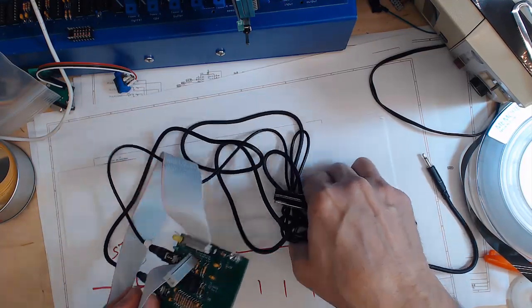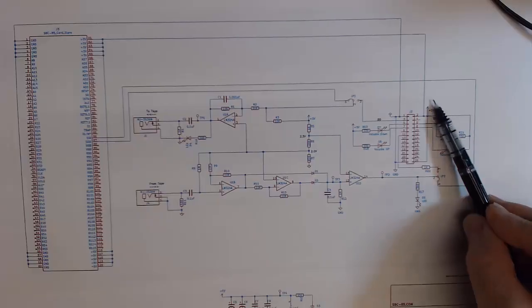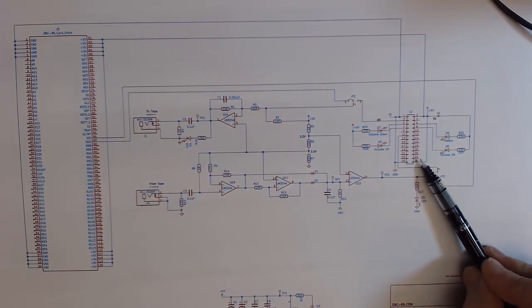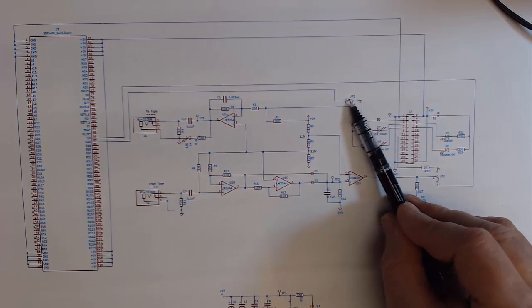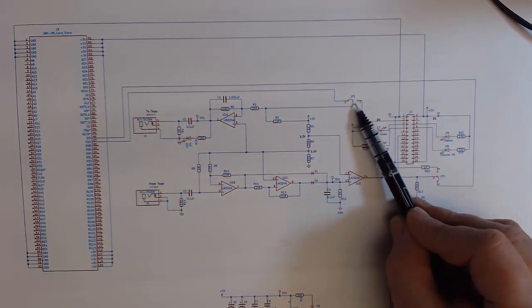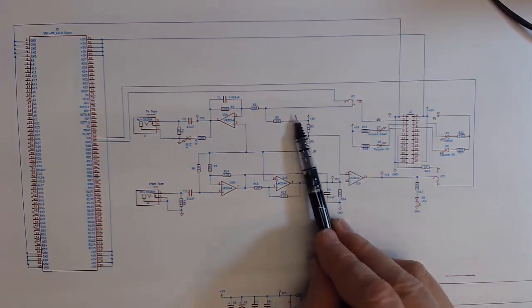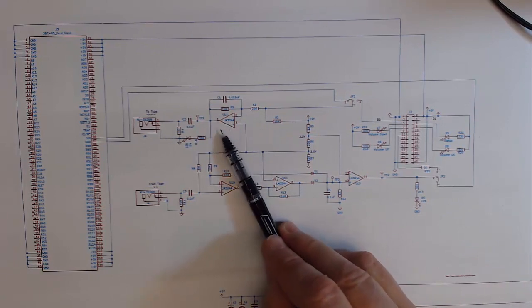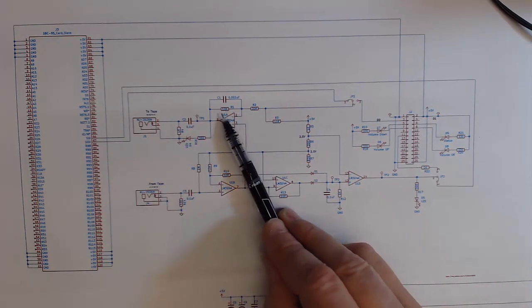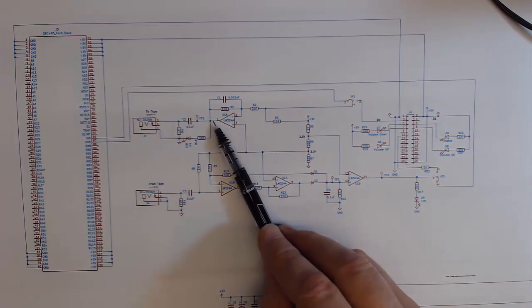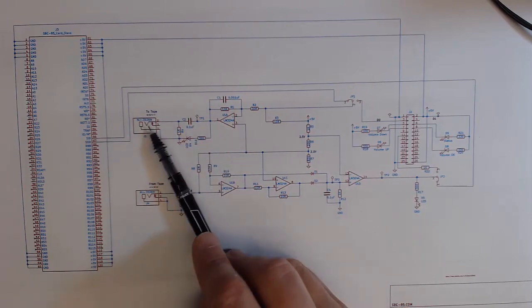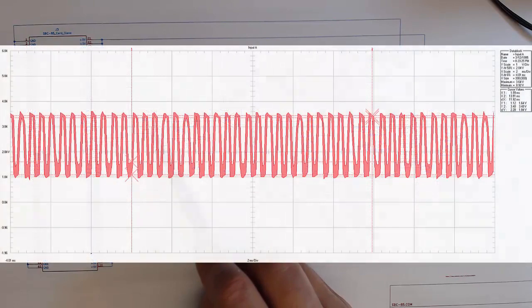But let's look at that schematic and see what we've actually got on this card. Here's our port coming in. We have our main data line. We have a jumper to either connect it to the SID and SOD or to that port. When it comes into our port, we can see it goes into this op amp, which is just a driver, and we're going to drive that signal capacitively coupled out to the tape, and by the time we come out, it's a 1 volt signal.